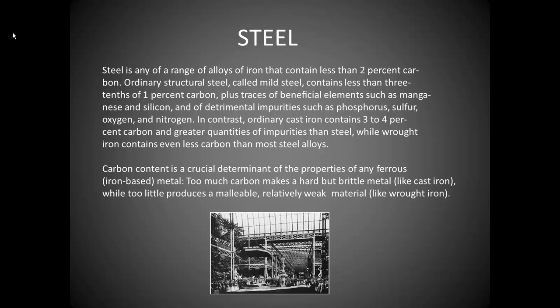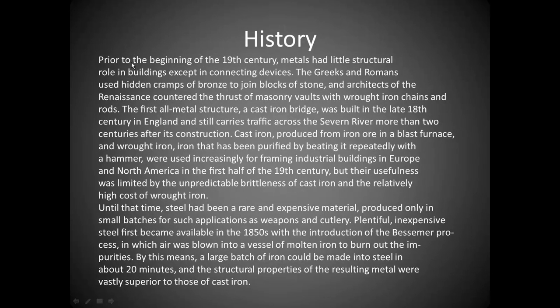The carbon content, of course, is crucial to the properties of ferrous. The name ferrous refers to iron-based metals. Too much carbon makes it hard and brittle, like cast iron, while too little produces a malleable, relatively weak material. So there's a fairly fine balance in that structure. A little history of steel.